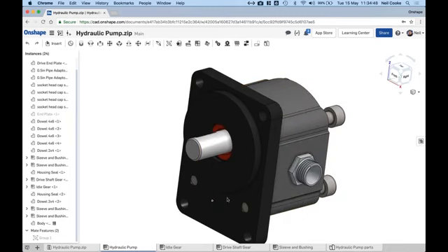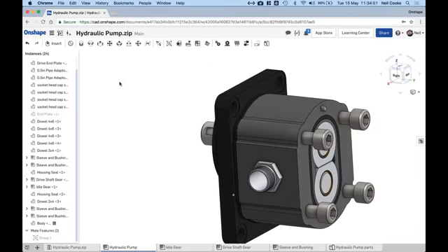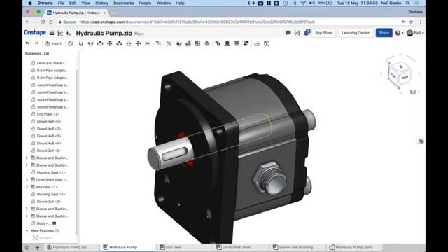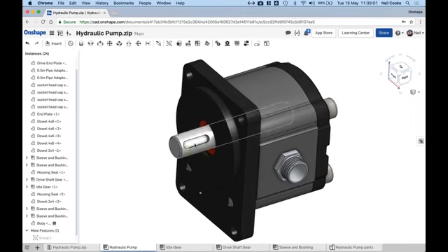One thing is worth mentioning: the fix command in Onshape is not the same as fix in SolidWorks. The fix command in Onshape is really only for the situation where you saw there, where I was trying to rotate this thing around, and it started moving everything else. So if I then inserted this into a top level assembly, the fix command no longer is active in the top level assembly. So something worth remembering. And for more detailed information on that, please take a look at the help file, and we've also done some blog posts on it, just a little bit more background.